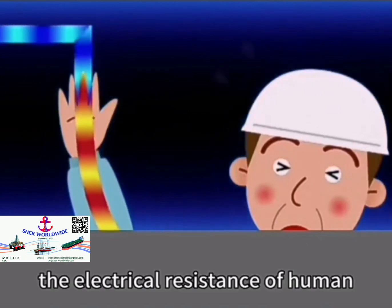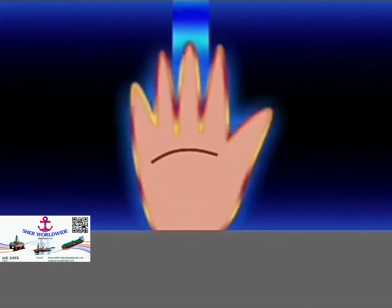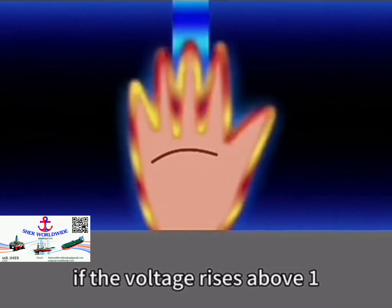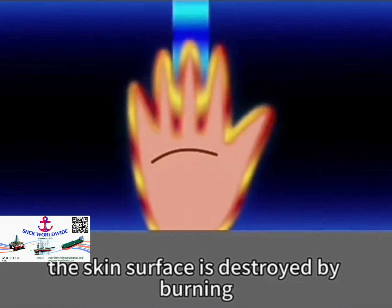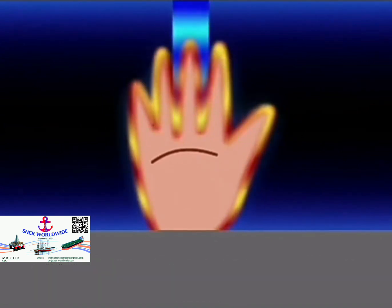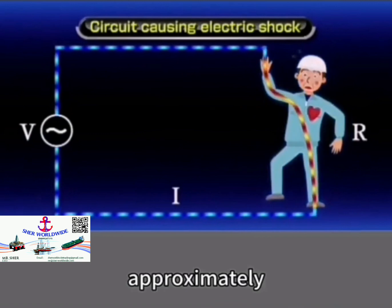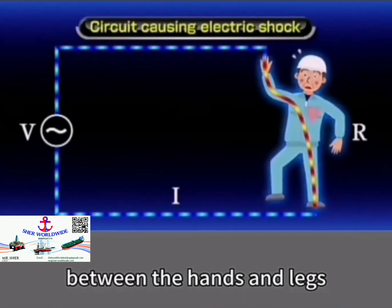The electrical resistance of human skin varies according to its wetness. Dry skin exhibits a resistance as high as several hundred kiloohms. If the voltage rises above 1000 volts, however, the skin surface is destroyed by burning, and resistance drops to as low as 0 ohms. The resistance of internal tissues remains almost unchanged, approximately 500 ohms for the area of the body between the hands and legs.